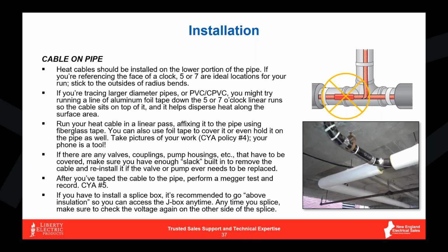Well, you can go out there with a Megger tester and test that cable to find out if it was damaged. So your Megger tester really is one of the most valuable tools in your arsenal. It's your phone, your pen, and your Megger tester. Those are the 3 things you need, and your screwdriver, of course.